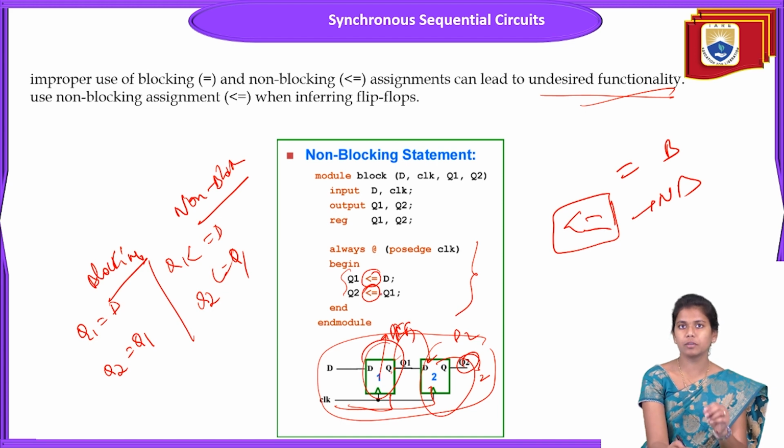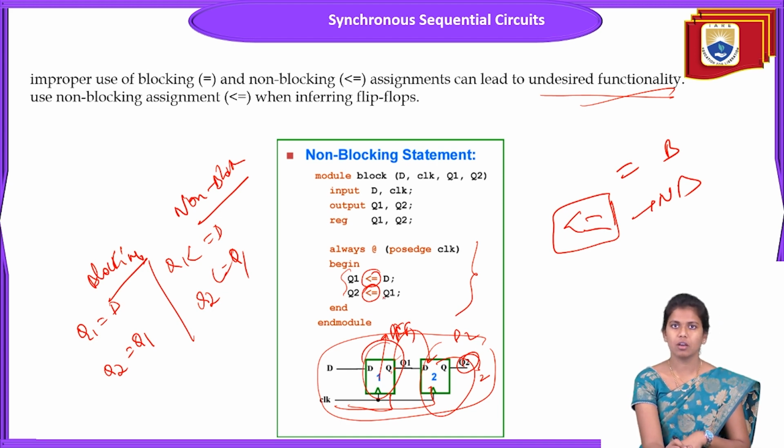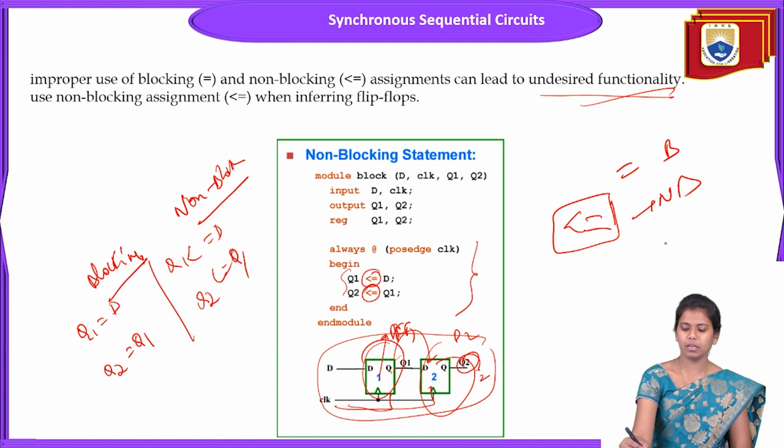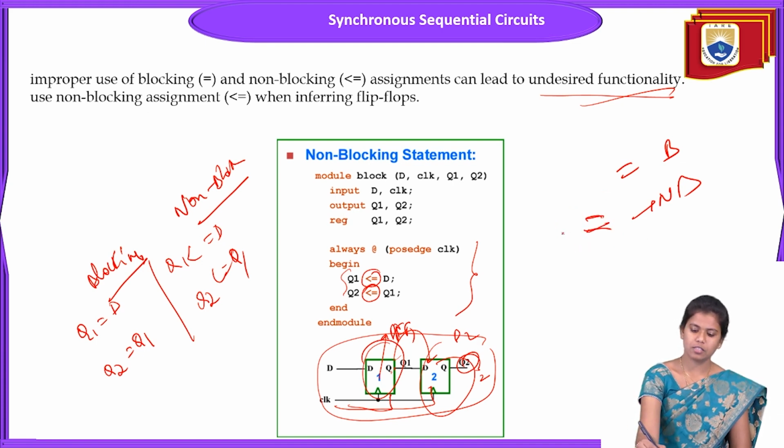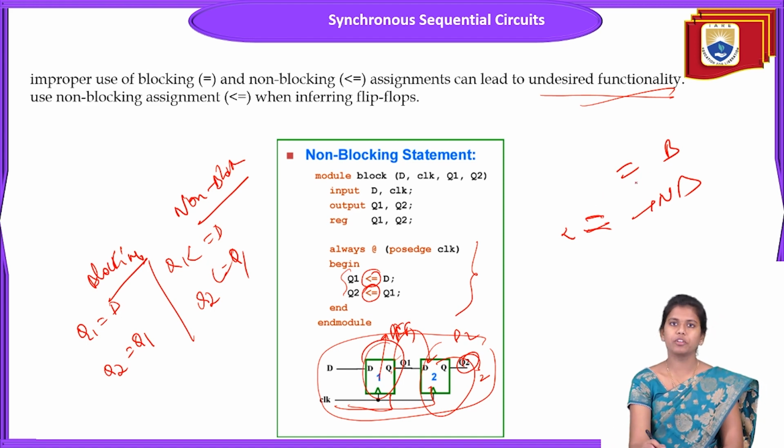But the representations of statements, always remember: for non-blocking statement it is less than or equals to, for blocking statement it is equals to. So this is a small differentiation between the blocking as well as the non-blocking statements.